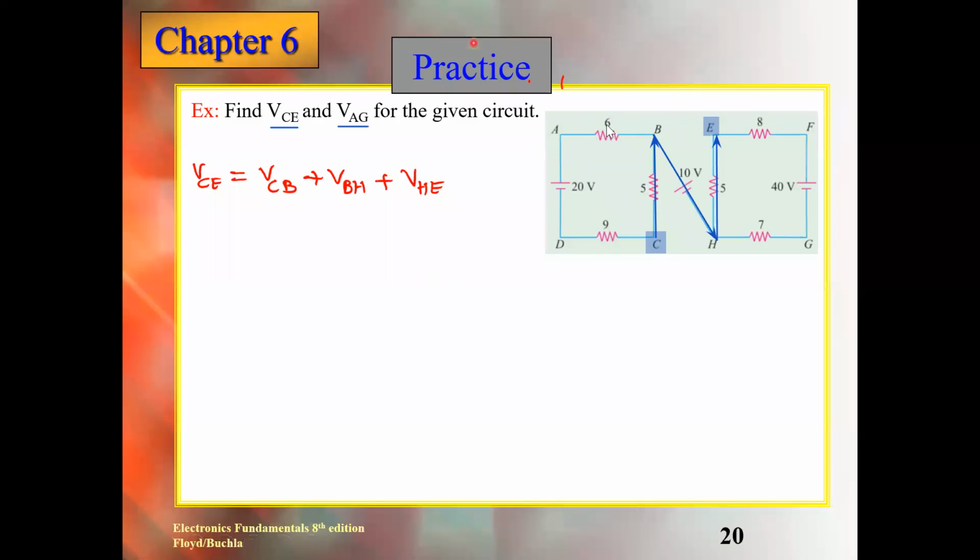In order to calculate the I, you need to consider how much current is flowing here. As I said, this is a source, so current will come from this source and go this way. And the same current will come here and go back here. So it is a series circuit. I equals V over R, doctor. So 20 over 6. Yes, this is a series circuit. And don't tell me 20 over 6.